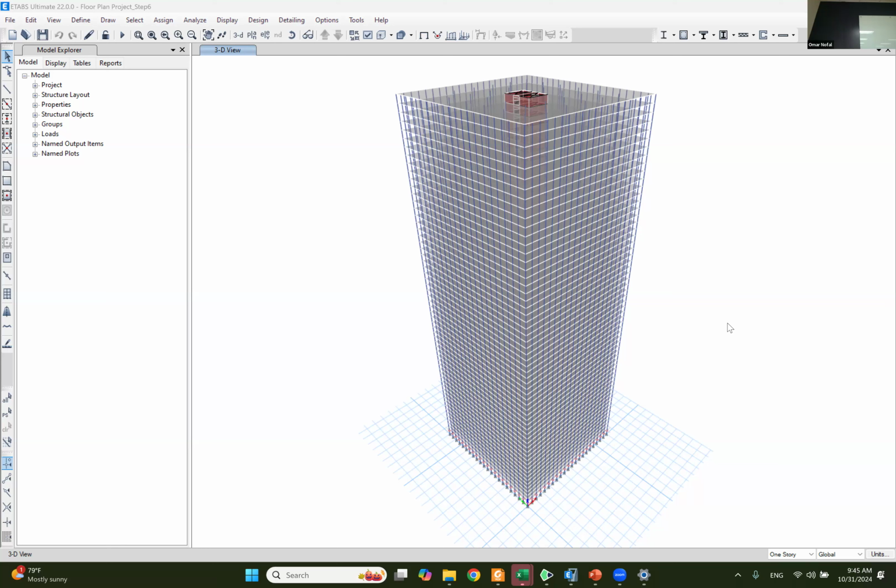Well, we can design at different time steps. Like you can say, oh, this building is going to have this moment at this time step and that moment at that time step. We pick the maximum, if you guys remember, and design for the maximum. And that's what the response spectrum does. It tells you the maximum acceleration that this building is going to have if it gets hit with this earthquake.